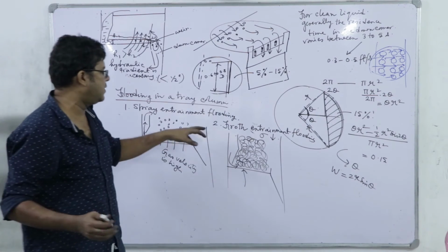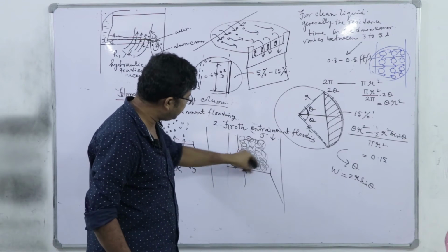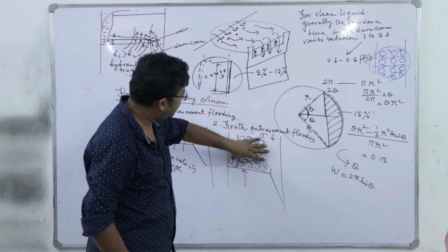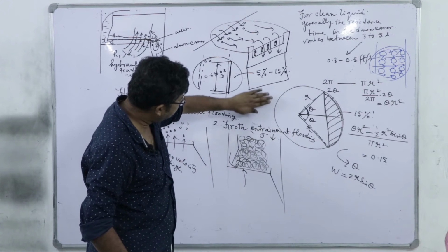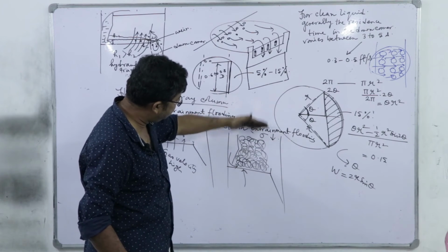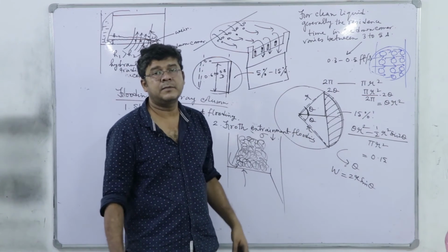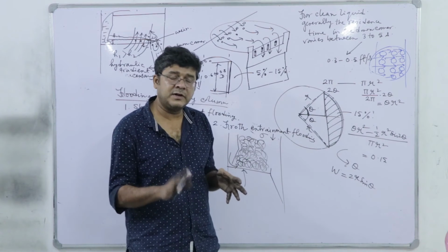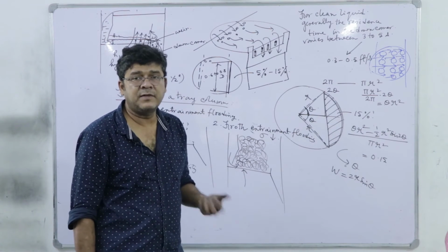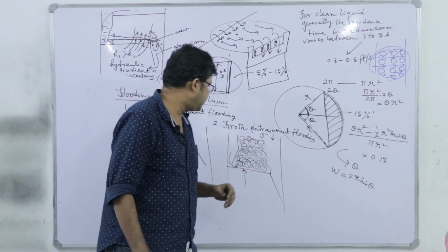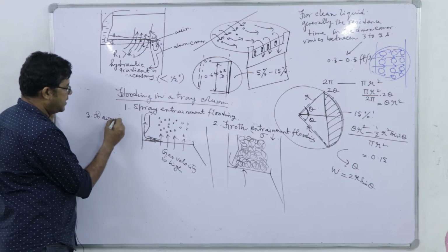Why is the flooding actually happening? Because of froth formation. The froth entraps the liquid that it receives from the incoming downcomer, and that froth floods the tray above, so it percolates, and in that froth the liquid gets arrested, okay, and liquid accumulates, because you are delivering liquid continuously into the tower. So the liquid accumulation starts and the flooding happens. The most common type of flooding is called downcomer flooding.